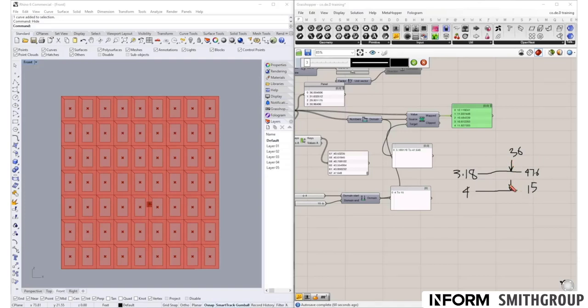It means that this value is going to be somewhere close to 12. So that's why we have this value here, because relative to the position of 36 in this domain, what is the value in that same position in this domain. That's exactly what Remap is doing. It's giving us positional information relative to domains. Okay, so 36 in this domain is equal to 12 in this domain.